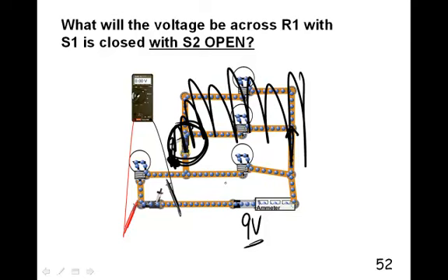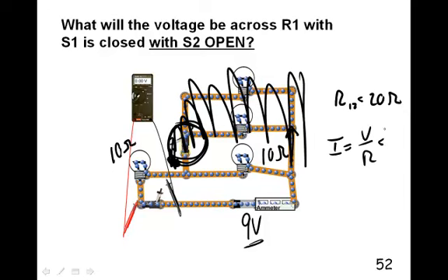And now we just have these 2 light bulbs that are in series. So we have 2 10-ohm light bulbs. My ohm there was not so good. I'm trying to go fast. Okay, so if you have 2 10-ohm resistors in series across a 9-volt battery, you could work that out, and you'd see that the equivalent R12 would be 20 ohms, and you'd find out the current that you'd get. Well, it's so easy. I'll just do it. It's V over R. So that would be 9 over 20. So our current should be 0.45.